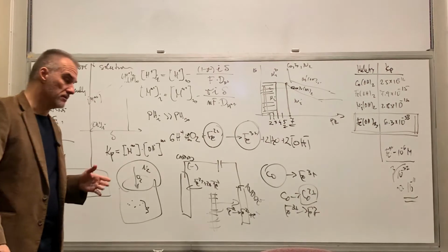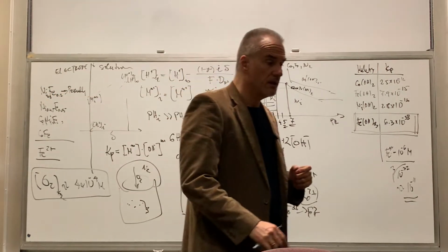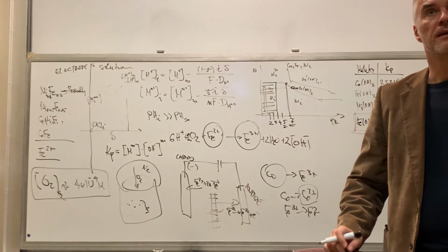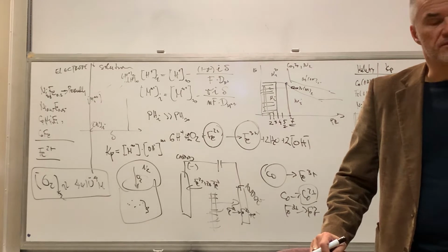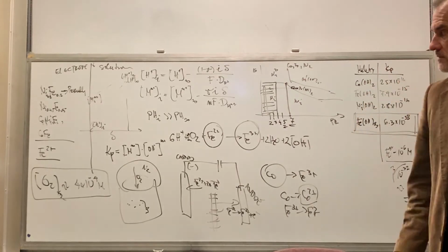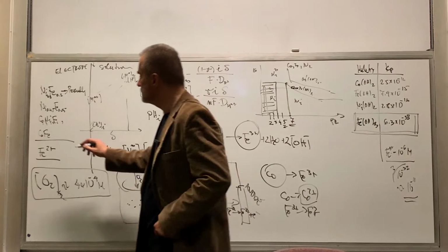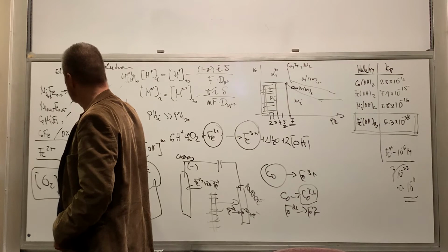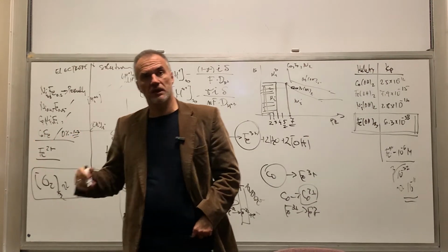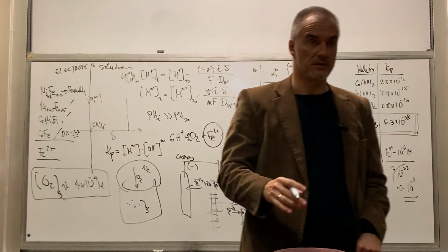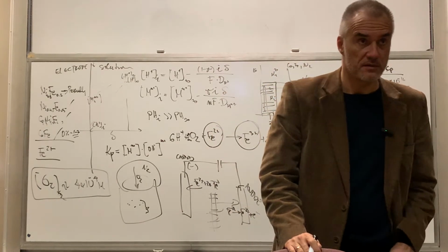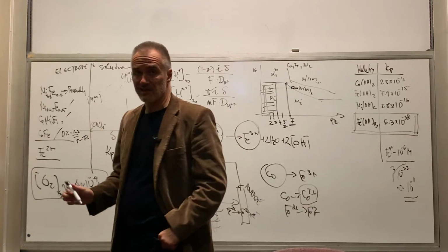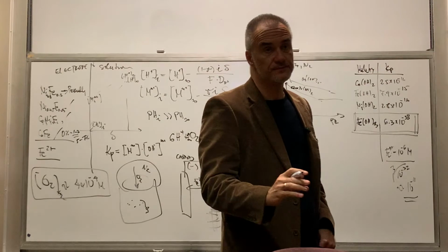Now, in industry, or when you do research, what you should understand is that ideality is rarely achieved. And so, most of the time, if these alloys here have oxygen percentage maybe 1 to 2, it's tolerable because the magnetic properties will not be significantly affected. But if this goes to 5 to 7%, suddenly everything changes.